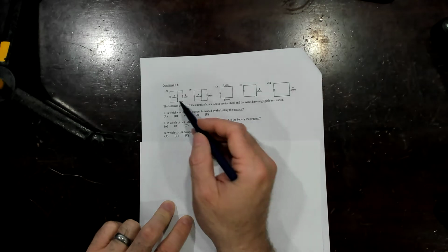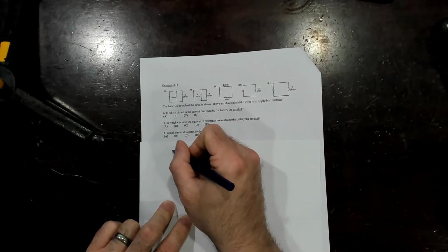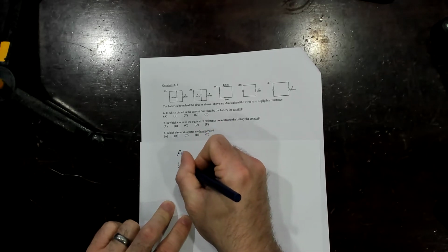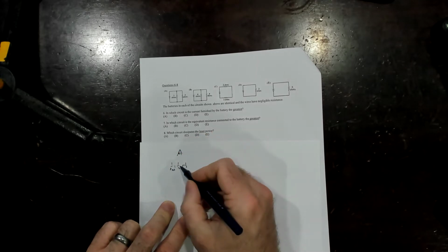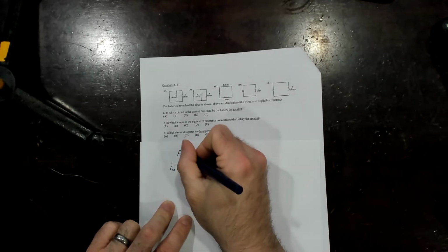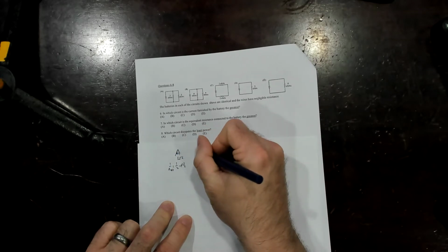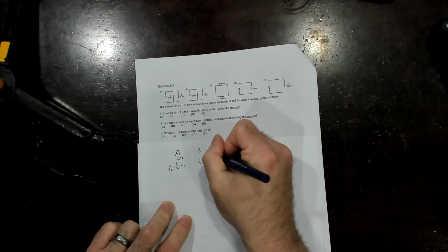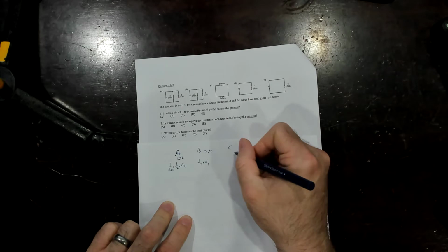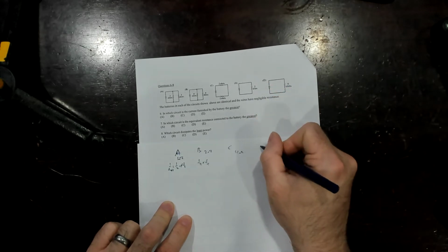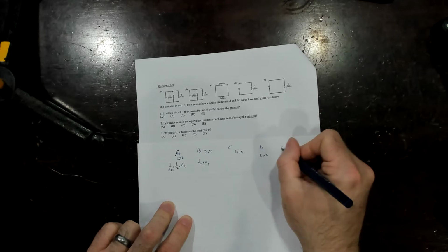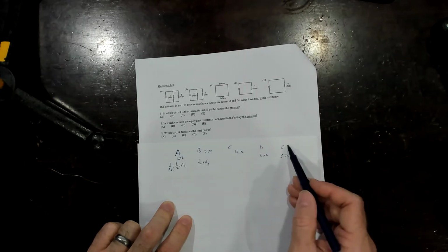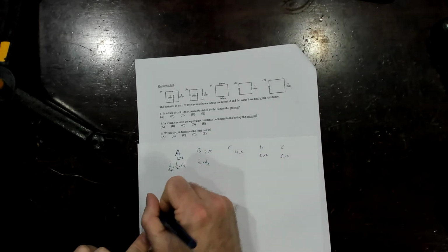Let's find our total resistances. A is a 2 and a 2 in parallel, so 1 over 2 plus 1 over 2 is 1 over the total, when you're in parallel. A half and a half, that's 1, flip it, it's still 1. So this one has a resistance of 1 ohm. B is a 4 and a 4 in parallel, so 1 over 4 plus 1 over 4 is 2 fourths, flip it, that would be 2 ohms. C is a 2 and a 2 in series, so just add them, that would be 4 ohms. D is just a 2 ohm, and E is just a 6 ohm. So which one has the greatest? Well, that's the 6 ohm one. That would be E, the choice for problem 7.